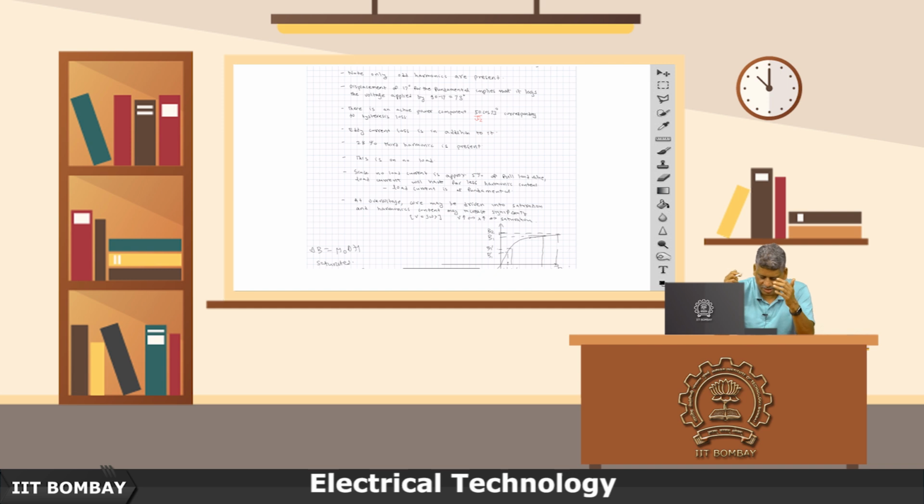When the transformer is driven into saturation, the curve is delta B equal to mu naught delta H. So, suddenly for that higher flux, the currents will tend to increase significantly, and the harmonic content may increase significantly, and harmonic content will only create losses. It is not something that we desire. Therefore, we should not allow overfluxing or over voltages on transformers.